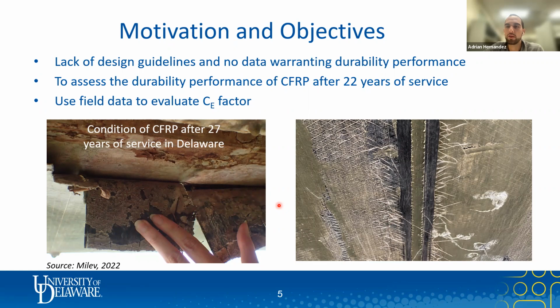Okay, I see. In general, though, after 20 years, is there a need to revisit these CFRPs and reapply or re-adhere them to the structure? I think it really depends on whether the CFRP is helping with sustained loading or not. If it is sustained, at that point you cannot peel it off and install it again because it's already taking some stresses. At that point, you might have to retrofit. But typically, for a service life of 20 years, more research has to be done.